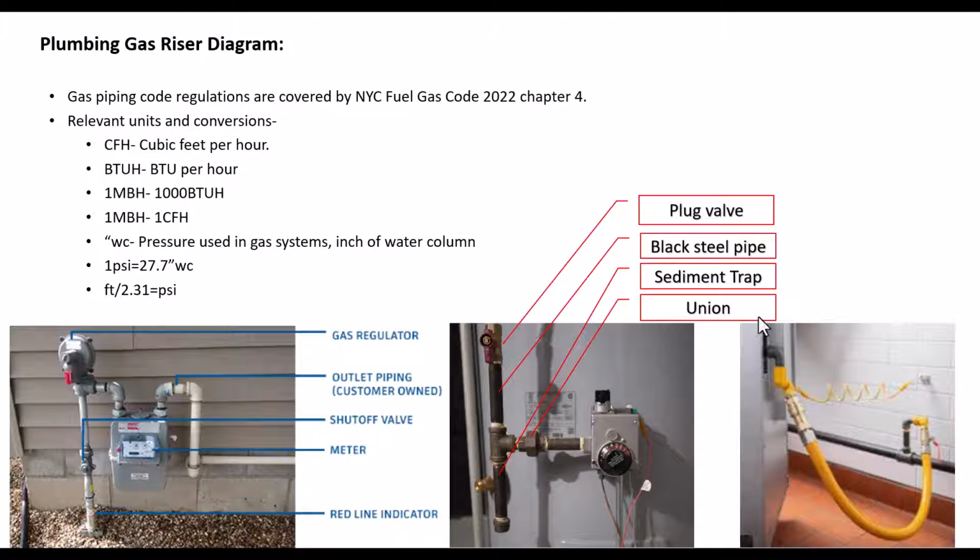In this picture, this actually looks like a water heater. For equipment that moves, if it has wheels or can be easily moved, the gas piping is connected through a flexible connection, which is represented by this yellow piece here. And this flexible piping has to be UL listed for use in whatever area that you are in. And this wire here is connected to the wall, and this basically restrains the equipment from moving too far of a distance that may cause this flex connection to break.